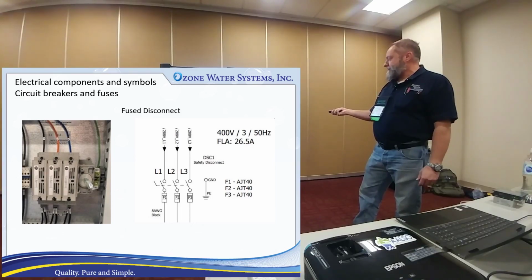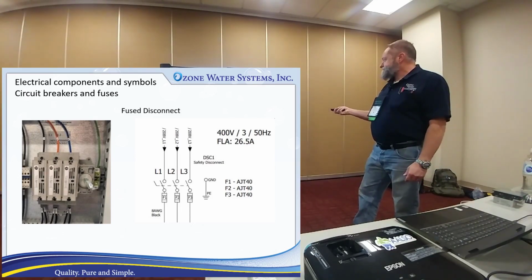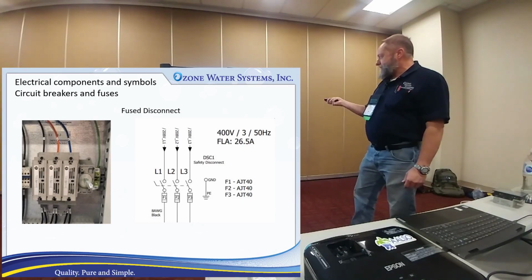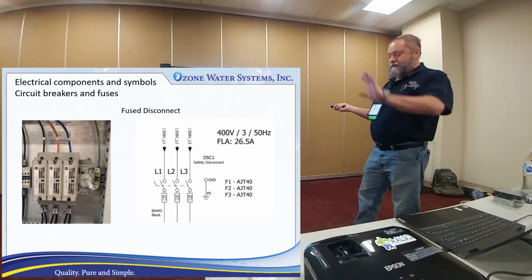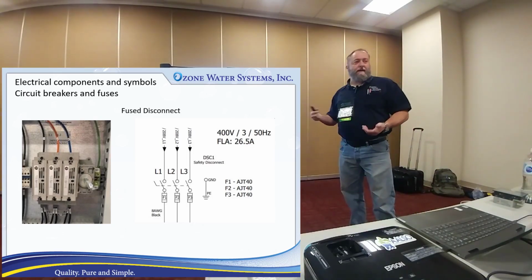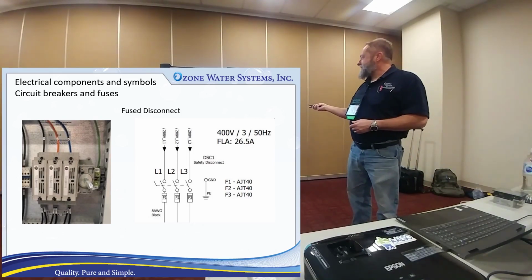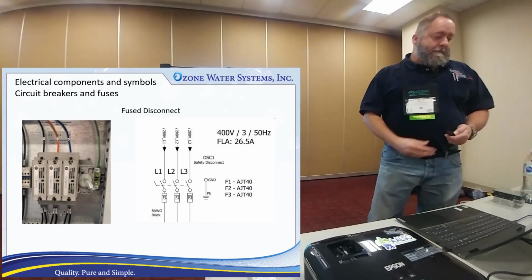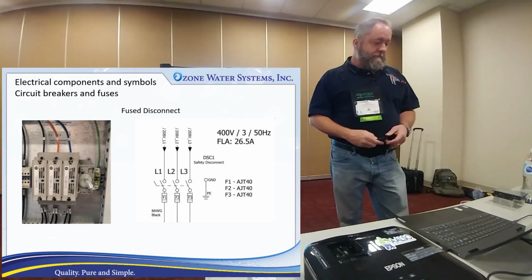And it'll usually have an identifier of what fuses go in that device. And then your full load current will usually be on that part of the schematic as well, somewhere in that top left corner. What's the main, the FLA, the full load amps. That's what FLA stands for, the full load amps of that system. And then what the mains voltage is.